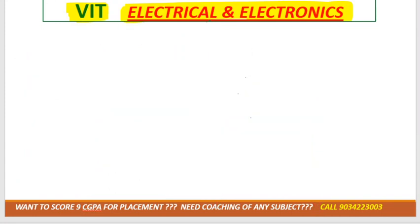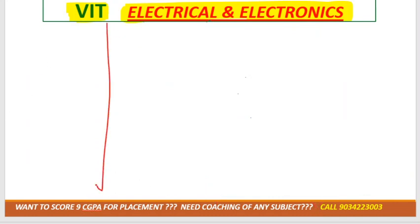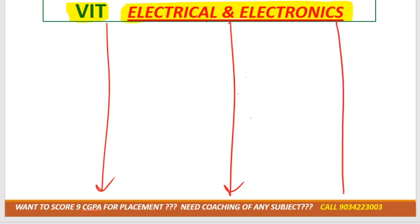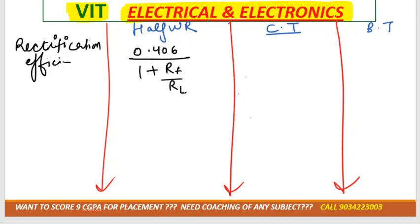Now, more formulas are left similar to this. Again for the half wave rectifier, HWR, full wave rectifier in center tap, and this one is bridge type. If they are asking for the rectification efficiency, the formula for the half wave is 0.406 divided by 1 plus RF by RL.